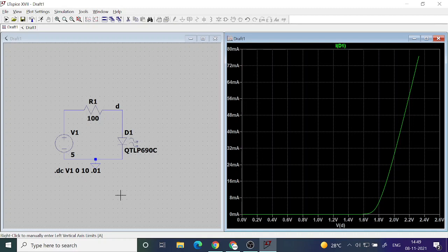You don't see much change if the current is in microampere. That is why earlier when I reverse biased, we did not see any reduction in the diode voltage. It was going from 0 to 10 volt, for example silicon. But once the current begins to flow in milliamperes, then you will see its effect on the voltages.